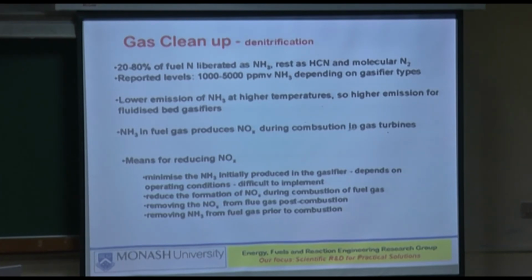So instead of giving all the oxygen to the entire fuel gas in one go, you give it in separate stages, so that in none of the stages you exceed. The more oxygen you give, the higher the temperature it can go.